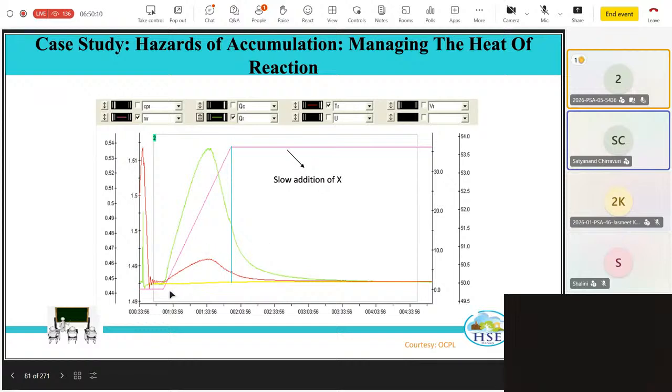Here you see the reaction, the addition of the halogen is done slowly here. So you go to the conditions at which the reaction is happening. There's an operating temperature, and then once you go to the operating temperature, right from gram 1 of addition of halogen, you will have the heat release that's happening. And then you keep on adding, and you keep on controlling the heat, and you see to it that the temperature rise doesn't happen that much, and it's under control.